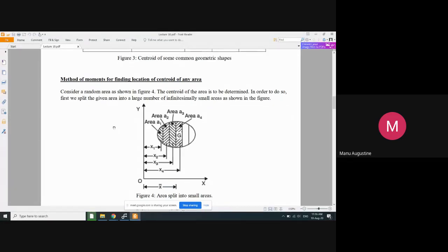In the last lecture, we had studied about finding the centroid of certain areas. For example, we learned that for a triangular area, the centroid would be exactly, if we take a right angle triangle, at a certain location from where the perpendicular distances, if measured, would be exactly one third of the respective bases.